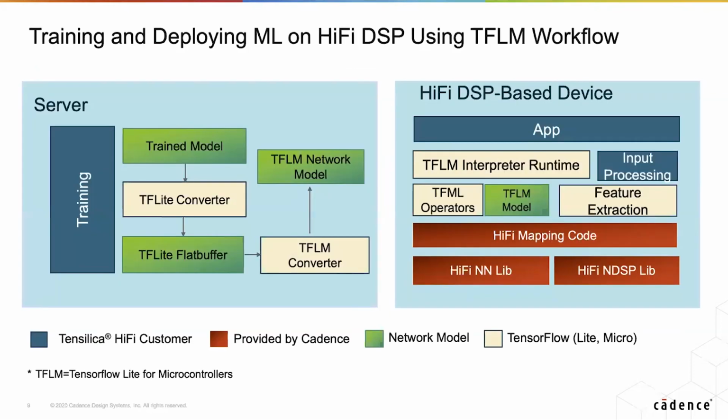So what does it mean by seamlessly deploy? The concept of the TFLM framework is generally up till the trained model. From there, it deploys, it gives you all the tools to, this is the flat buffer that's known in TensorFlow Lite. And from there, there is a conversion tool that converts your trained model into a much smaller model that your edge device can deploy directly. That it has smaller model and C++ code that's ready to deploy.